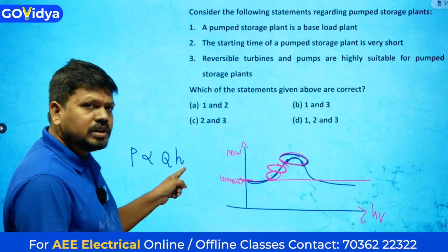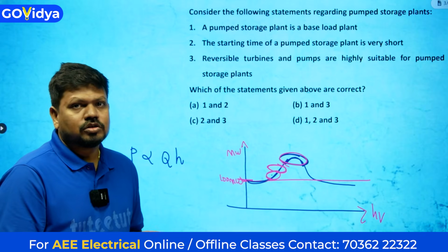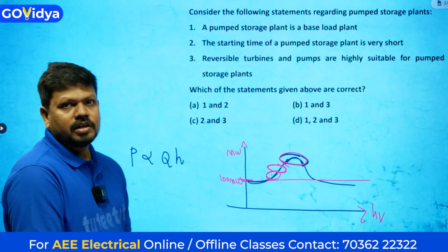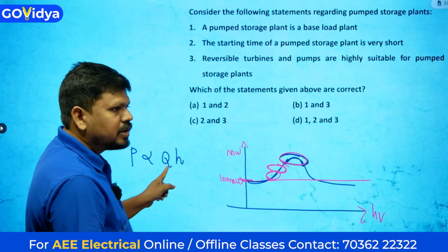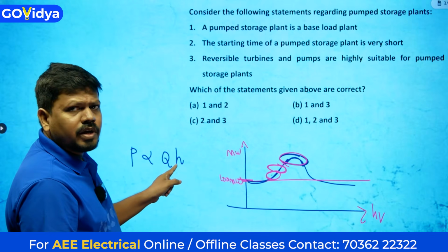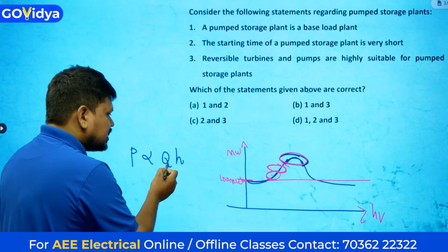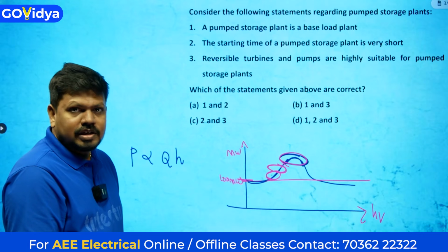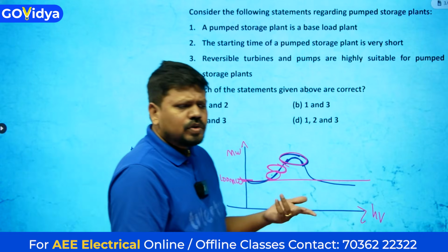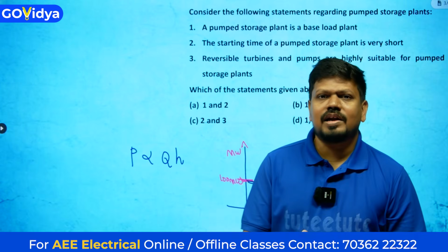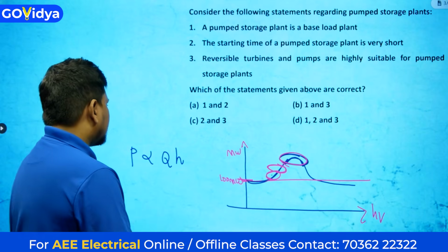But why have we done this? Because we don't have much discharge. So more water we cannot use now, that's why we have increased the head there. For example, if a continuously flowing river is there, more water availability will be there, no need of that much head. Understanding? Continuously flowing river means more discharge, more water availability. So we can utilize that water properly, and no need of much head. That's why no need to construct a big dam. A small dam is enough, sufficient head is enough. Understanding? Based on this we can understand.